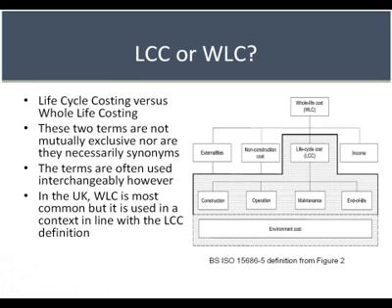So on definitions here, there's these concepts of whole life costing and life cycle costing. And I'd say you're going to see whole life costing a bit more mentioned in the UK rather than in the US. But the ISO standard 15686 actually defines it here, where whole life costing gets a bit more into externalities, business income, and some other sources not just related to capital costs and energy. So for most building work, it does concentrate more on the LCC side of things. That's the term I use.